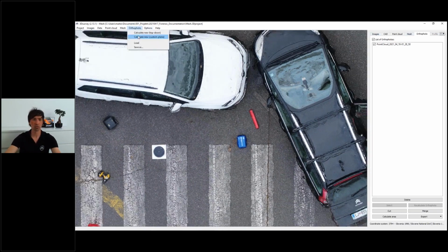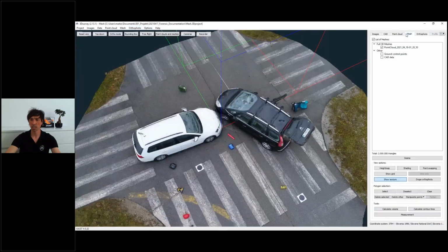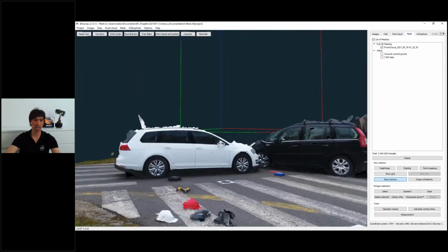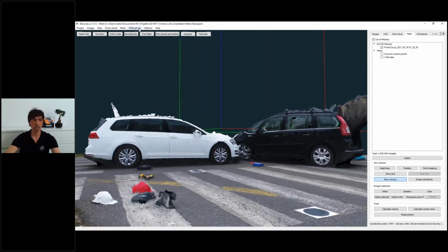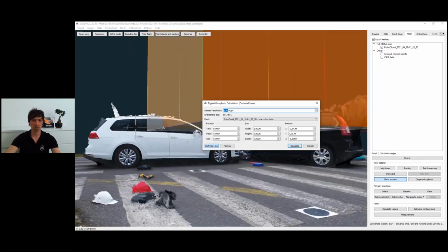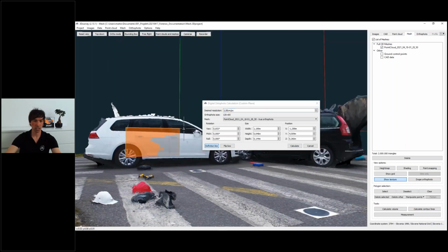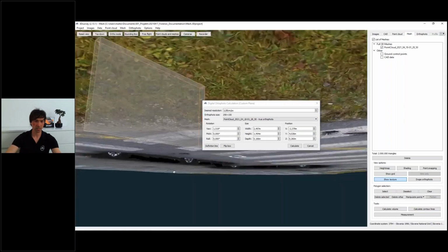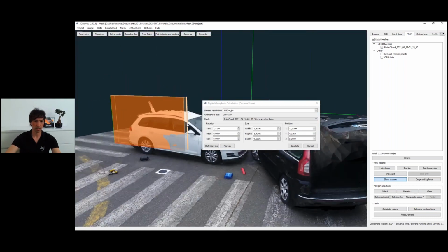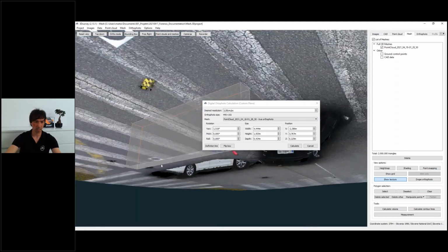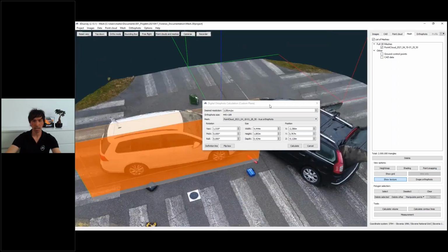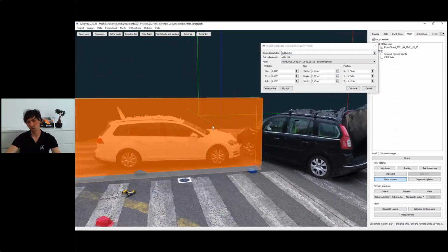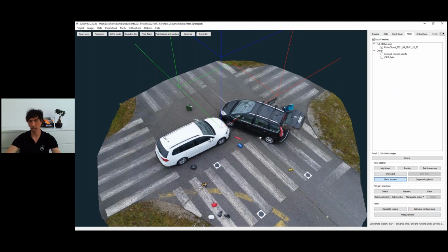Here is also option to generate a side orthophoto. So in case you would need to generate something like that and put it in 2D, you would use this custom plate orthophoto and actually define your side plate in this way. For example, okay, I'm using the right mouse button to extend the planes under it like so, and in this way export a side orthophoto. Feel free to try it out by yourself. It's super easy, works really nice.